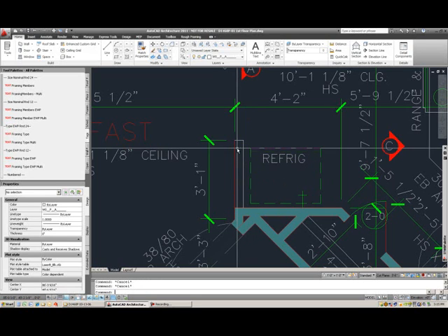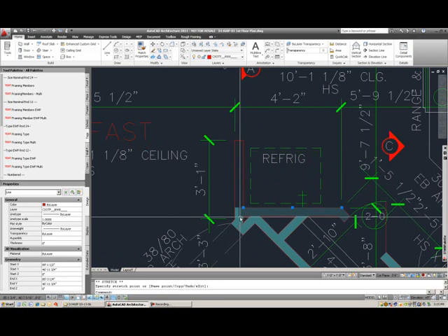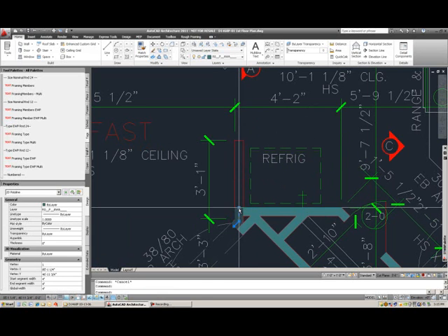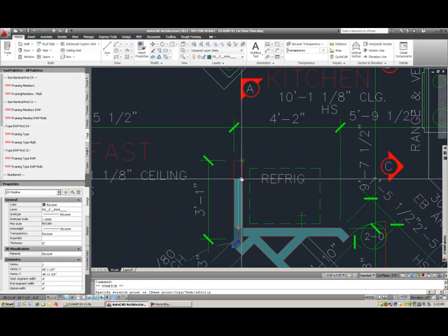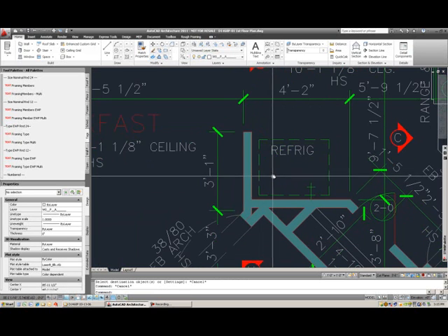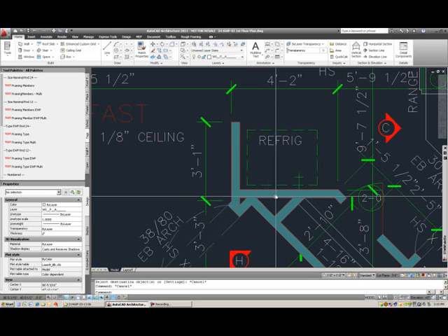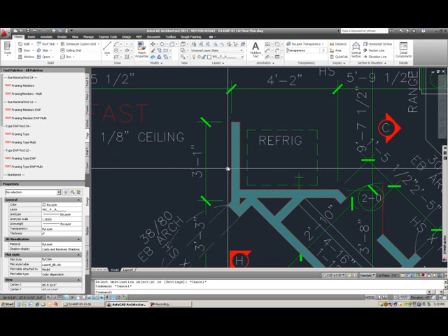Okay, that's white, so I need to match that layer with that layer to get it in the correct layer. Do my drafting, get this blue line that's kind of thick that would print out on screen to actually make my wall here. So that's a typical process where you need to stretch this line, you need to match it with that layer and get all that straightened out.